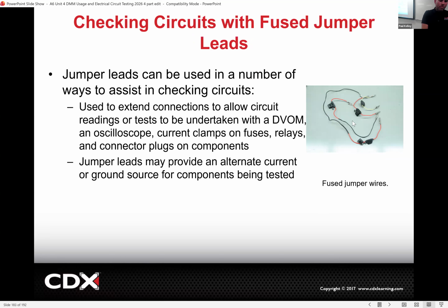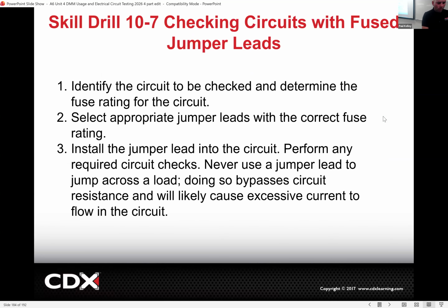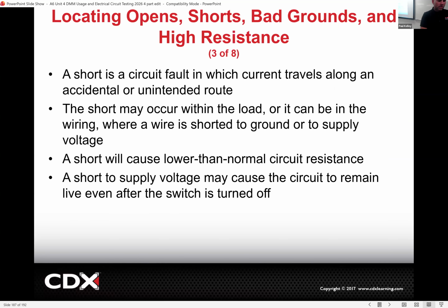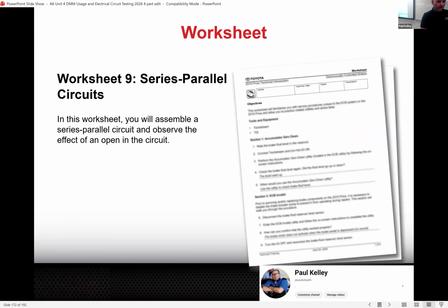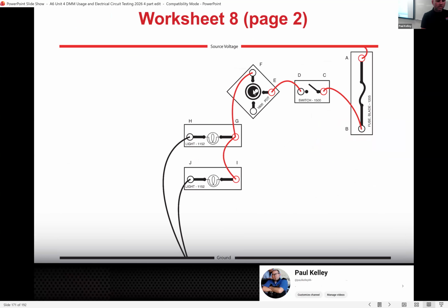Right? Now, fuse jumper we didn't talk a ton about, but let's just say you've got these little alligator clips. They go on a wire which goes through a fuse jumper, which goes to another alligator clip. What would we do with these? Let's just say if I were to jump way back to this diagram, and let's say that we thought that this switch was no good, what if I took a fuse jumper and I tied it into C, and then I jumped it over to D?